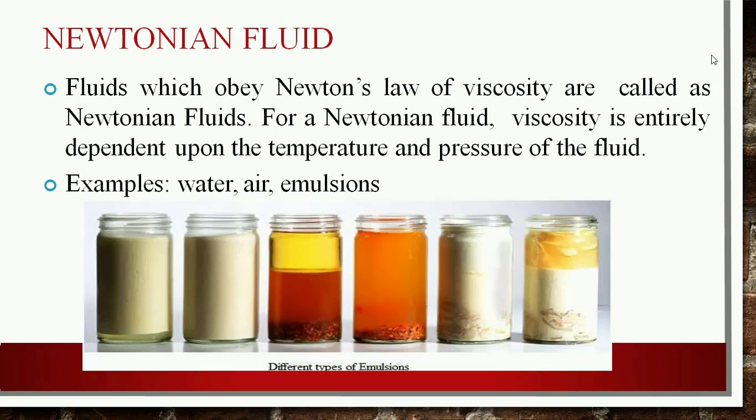First is Newtonian fluid. Fluids which obey Newton's law of viscosity are called Newtonian fluids. For a Newtonian fluid, viscosity is entirely dependent upon the temperature and the pressure of the liquid. Examples: water, kerosene, petrol, air, mercury.